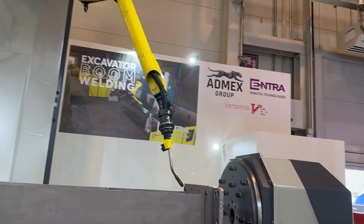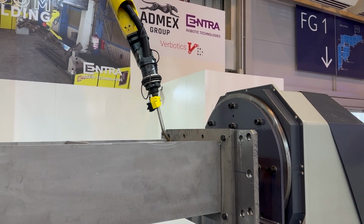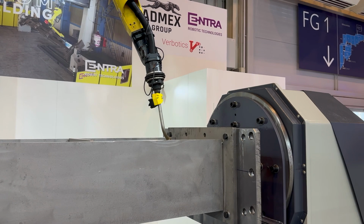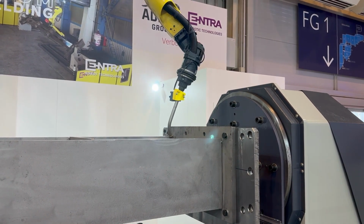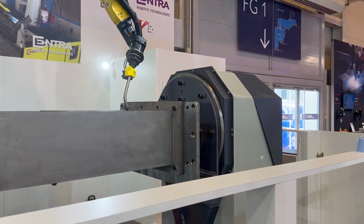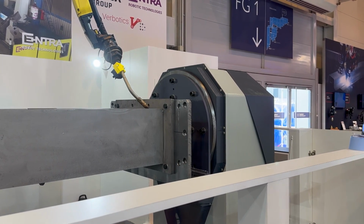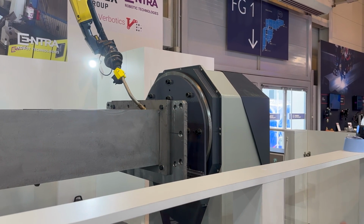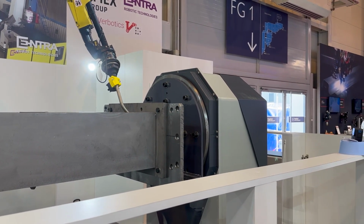So you'll see the robot starts by approaching the first weld seam. It then uses a one-dimensional laser sensor to detect where the part is in real life. And that allows the robot to account for the difference between the 3D simulation and the real world without any need for manual touch-up or editing. And that's part of the magic that allows the program to go straight from the Verbotics software to a ready-to-run robot program, all with minimal time and effort.